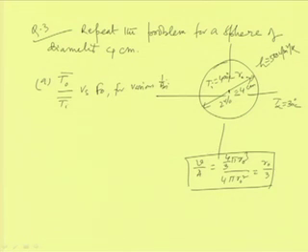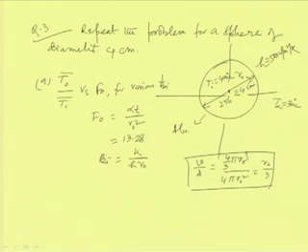Fourier number is alpha t by r naught square, and in the case of the sphere the value remains the same, 13.828. The Biot number is again expressed as k by h into R naught, where k and alpha are the same, because this sphere is also made of aluminum.